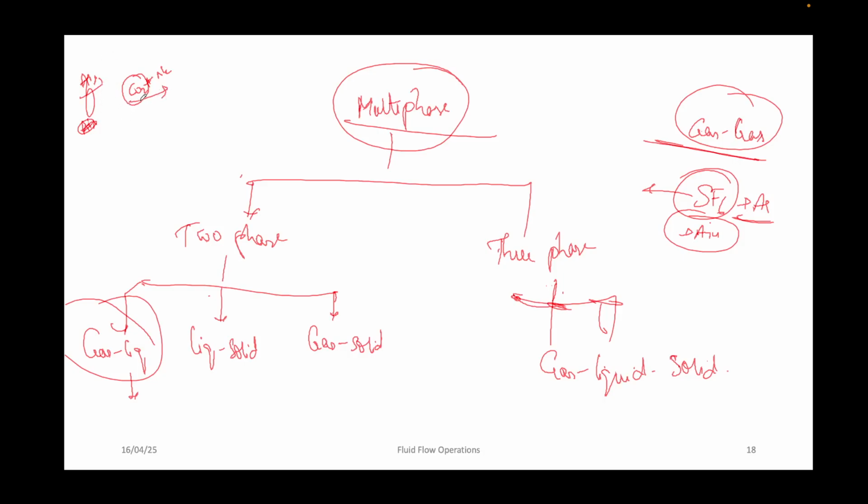How do you remove it? You'll just pass this gas, or bubble this gas, through an amine solution, basically a liquid solution. When it comes into contact with this amine or alkaline solution, the CO2, which has affinity towards basic solutions, will be absorbed instantly into these amine solutions.